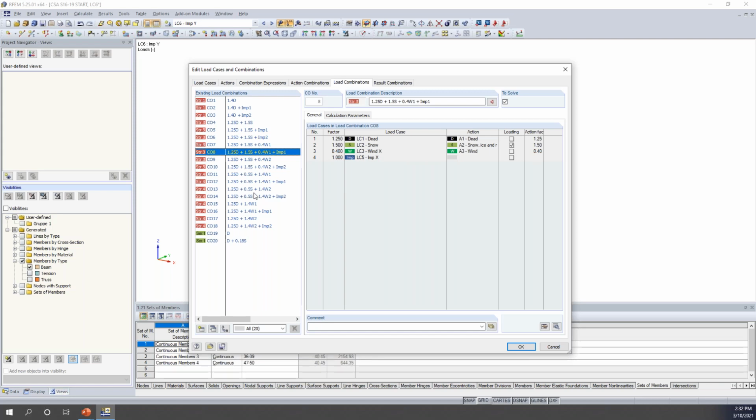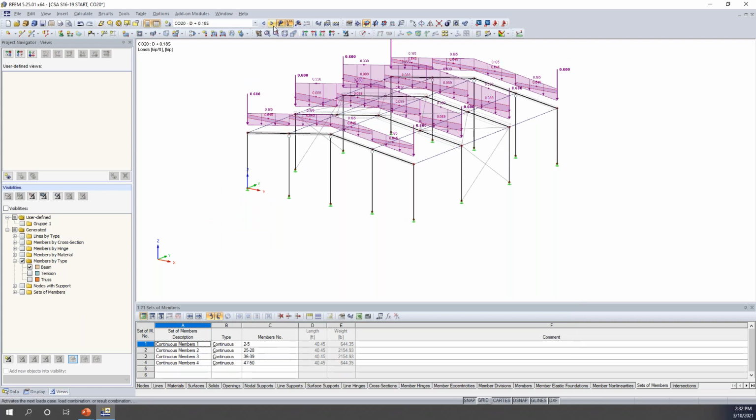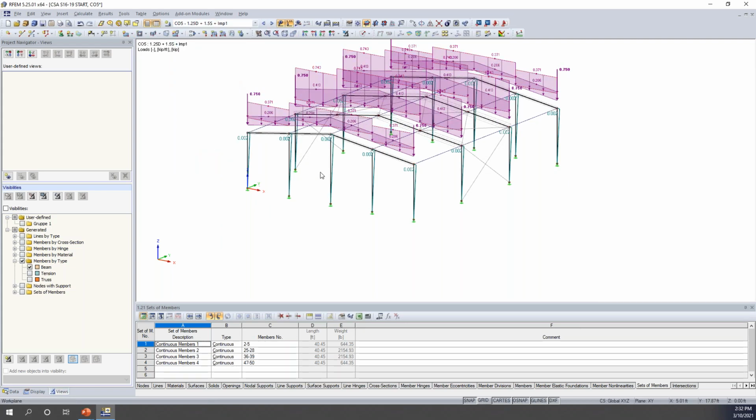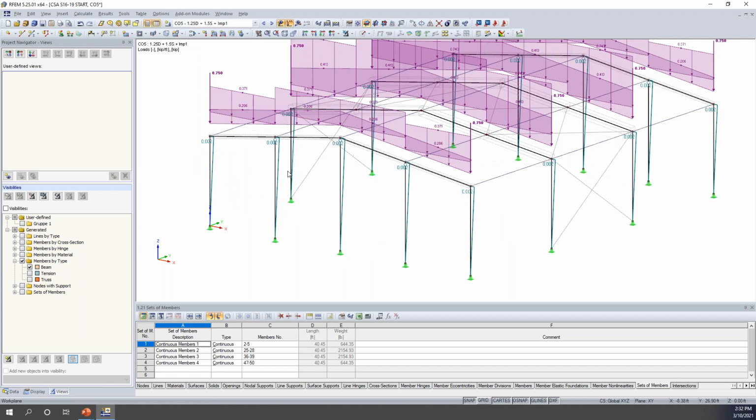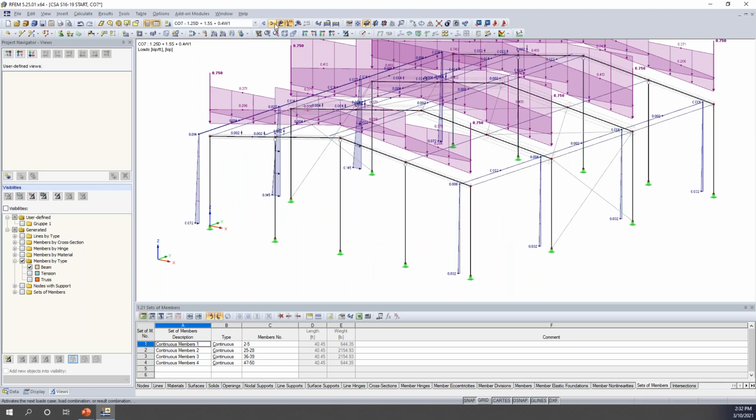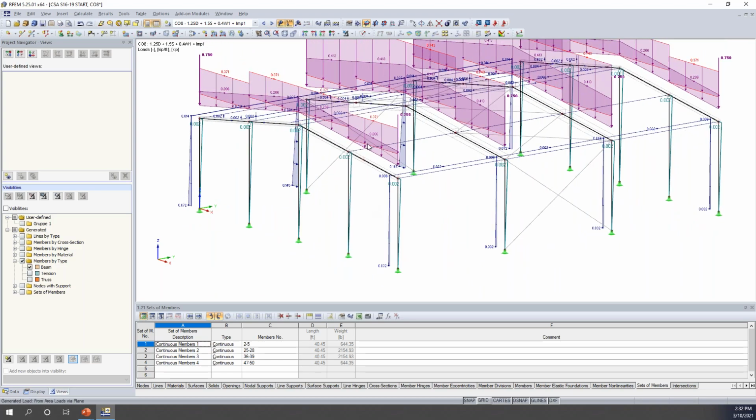We take a look at our next load combination. We have dead, snow, wind in the Y, and then we have dead, snow, wind in the Y with our imperfection in the Y. Now, sure enough, with our serviceability or unfactored load combinations, no imperfections are considered at all. So this is exactly the scenario that we wanted. We've accurately applied those notional loads to the structure. Okay, so we also can view here graphically those imperfections, the snow load, wind loads, everything applied to the structure at once if we're interested in seeing this graphically all together.